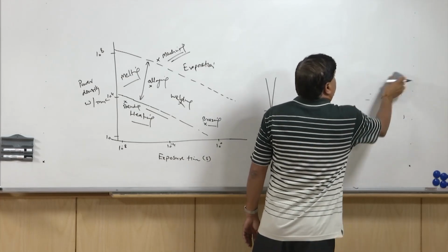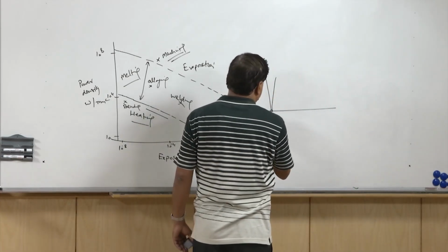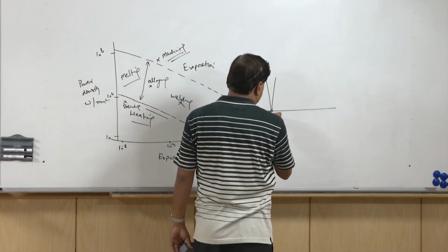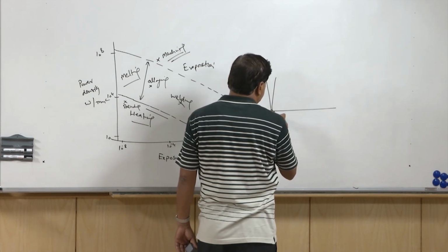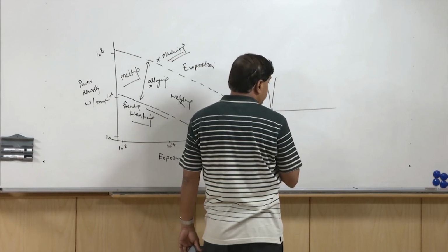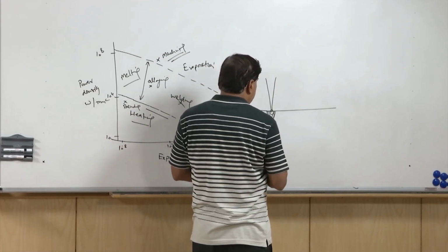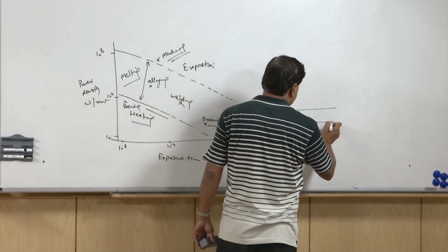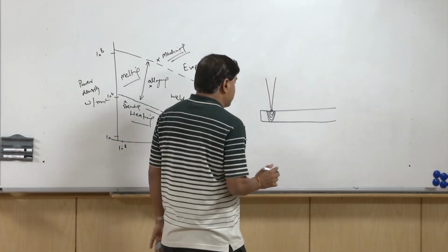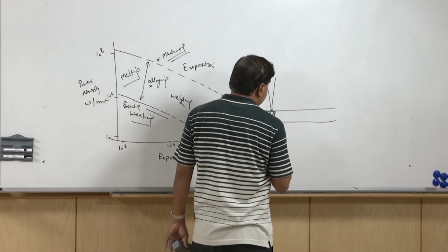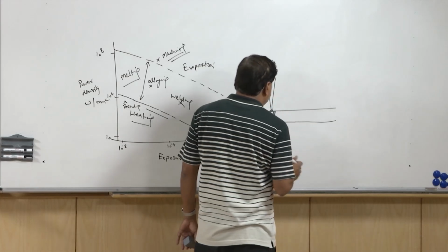In this case, the laser is directed over a very small area. So the melting takes place. You see melting will be taking place like this. If you keep on increasing the duration of the stage, the depth of penetration will keep on increasing up to a certain limit. So we have to identify how to adjust the scanning speed, so that we get a suitable depth sufficient for penetrating through the thickness, and once this depth is achieved, we can start moving the laser as per the required speed.